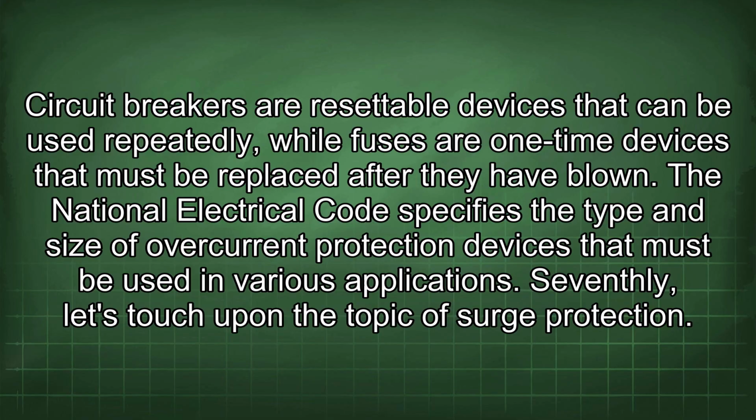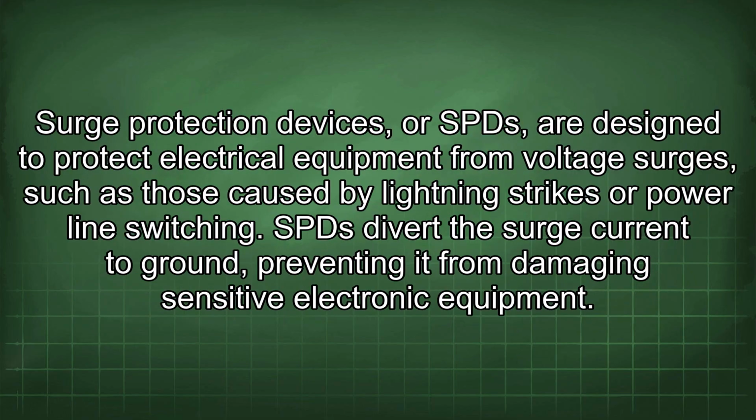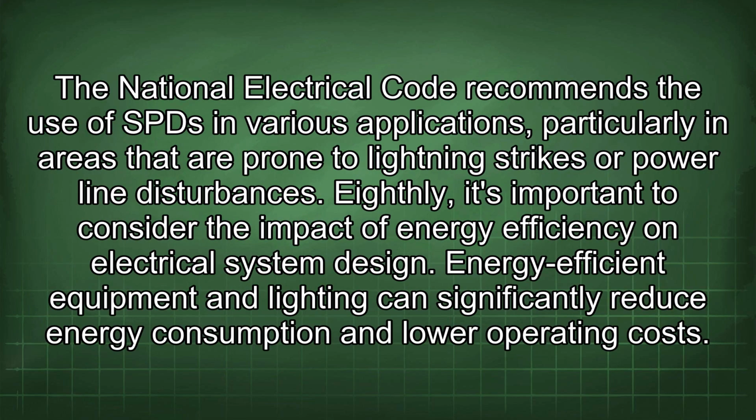Seventhly, let's touch upon the topic of surge protection. Surge protection devices, or SPDs, are designed to protect electrical equipment from voltage surges, such as those caused by lightning strikes or power line switching. SPDs divert the surge current to ground, preventing it from damaging sensitive electronic equipment. The National Electrical Code recommends the use of SPDs in various applications, particularly in areas that are prone to lightning strikes or power line disturbances.